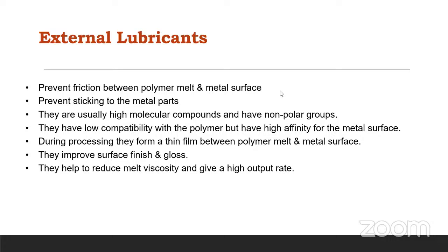There is a range of certain chemicals or additives which are compatible with our polymeric system. They have a positive spreading coefficient, or a chemical affinity, so that they properly get dispersed into your polymer matrix during compounding, during mixing itself.